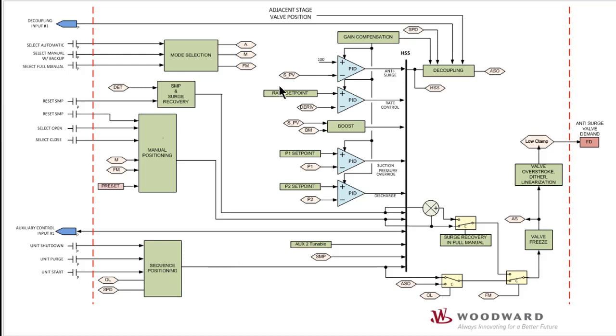Each of these routines and PIDs comes into a high signal select bus, and the highest signal of each of these independent inputs will get passed along to the final valve demand.